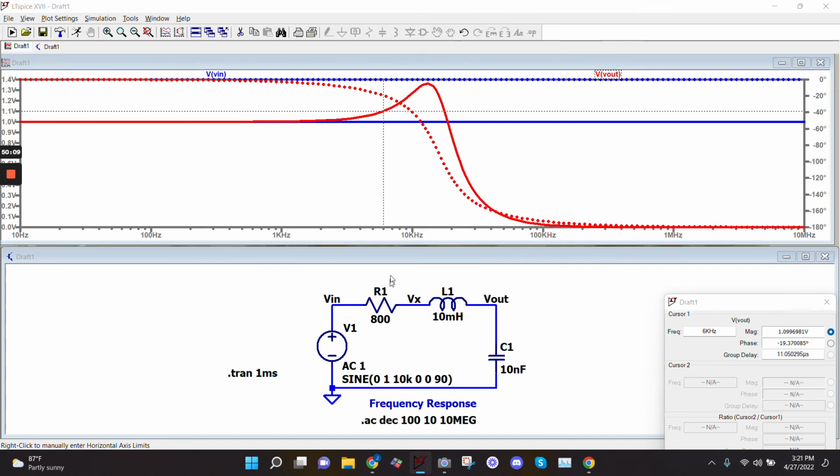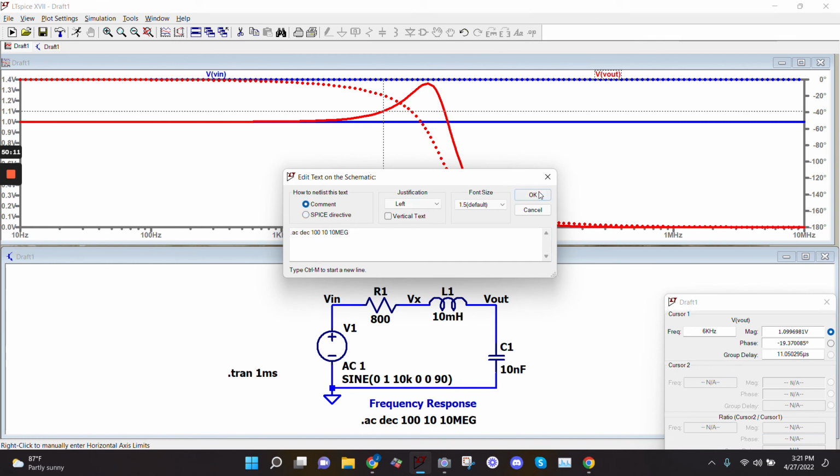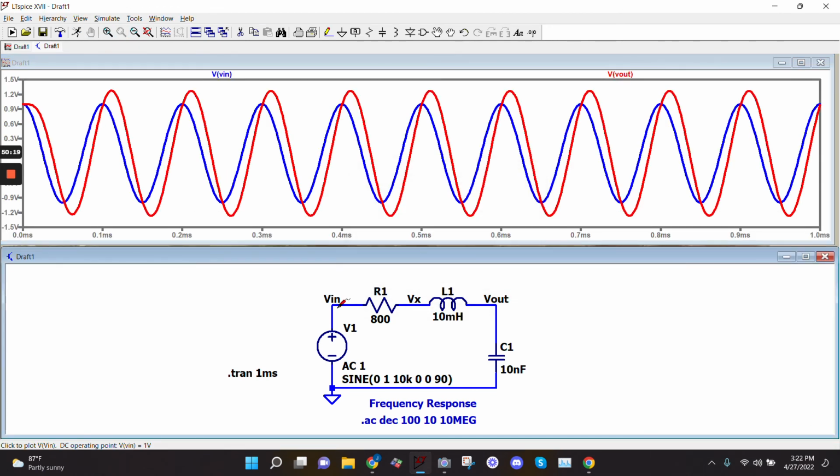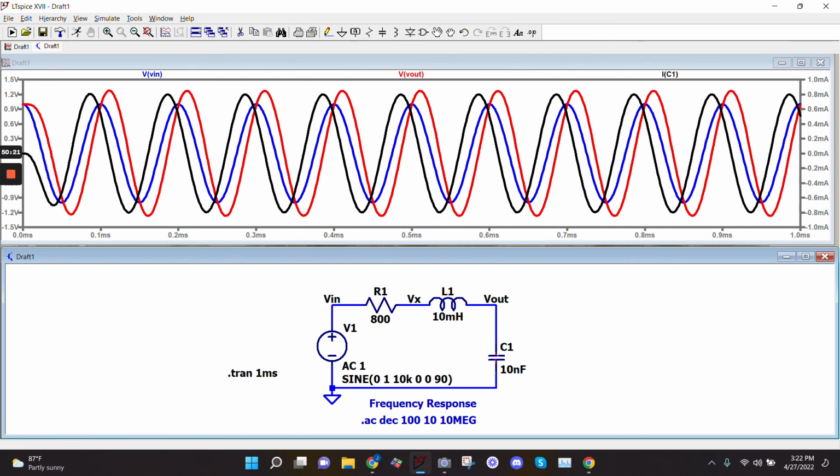So what we should see is that the current should lead the voltage, like you said. And so we get input, output, current. And so my output voltage lags my current. And you can know it's a capacitive circuit just based on that. And it would be vice versa for the inductor. So for your homework, you should have gotten that in one of them, the current lagged the output, and in the other, the current led the output, because one of them was capacitive and one of them was inductive.